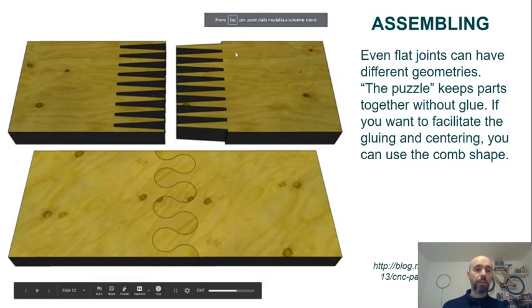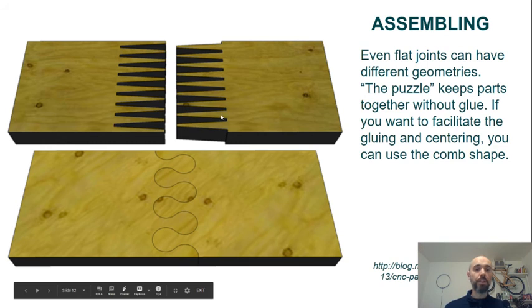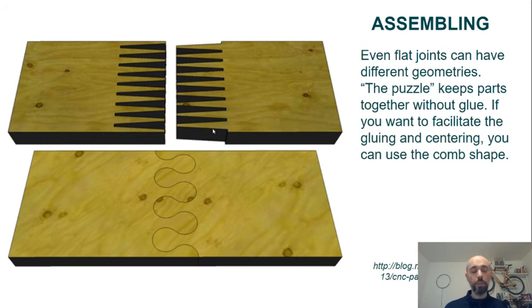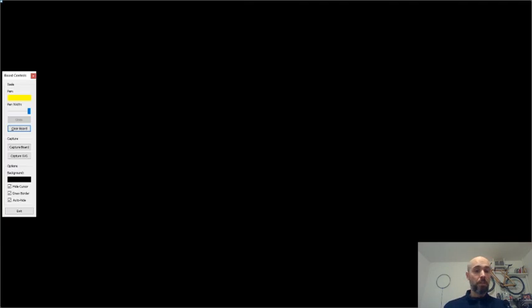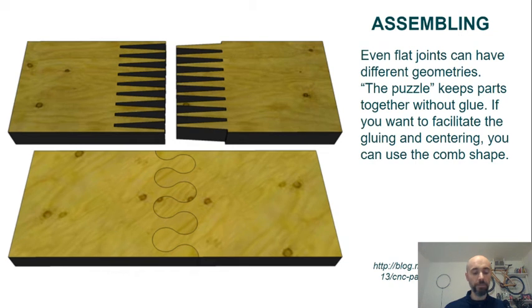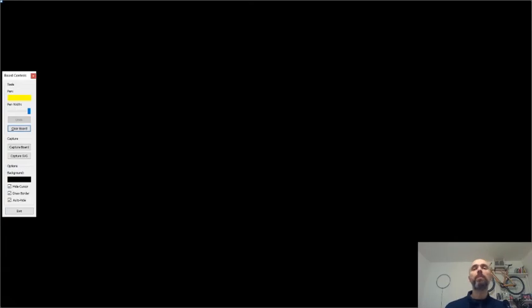So we were saying this part here could be the connection between two elements to create something bigger than the laser cutter, or just a way to connect back pieces that were easier to cut if you divide them. Now, why do you have that weird shape? That weird shape, the finger connection, is actually very important when you work with wood.